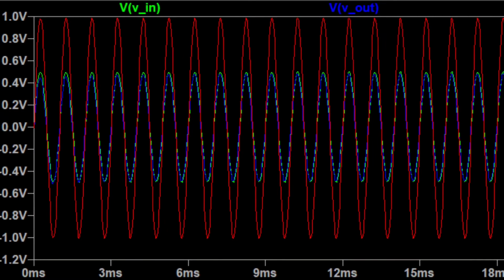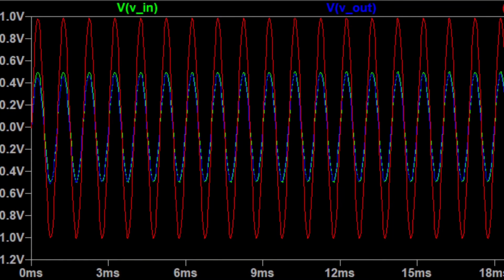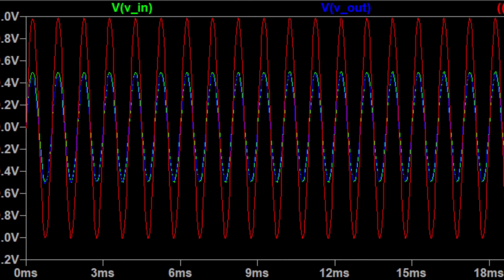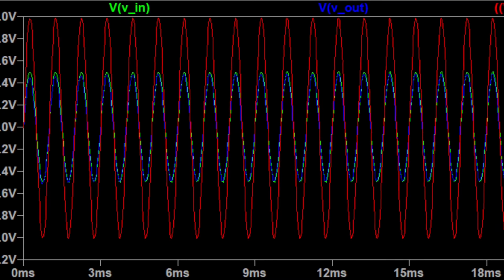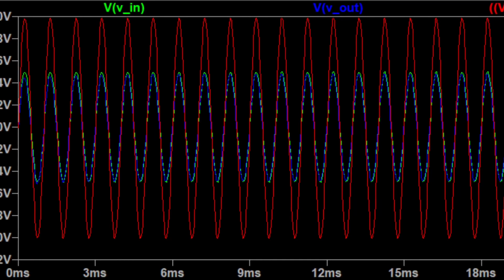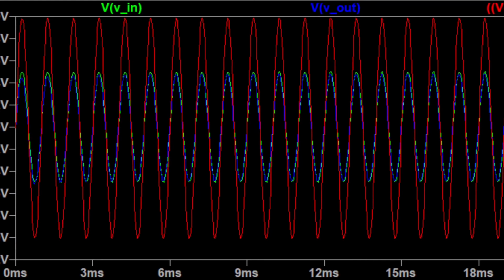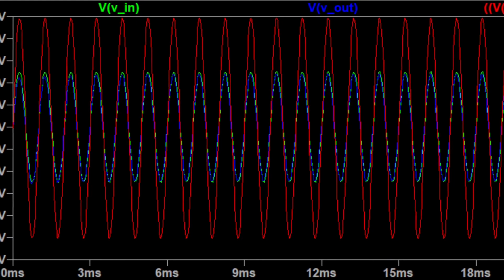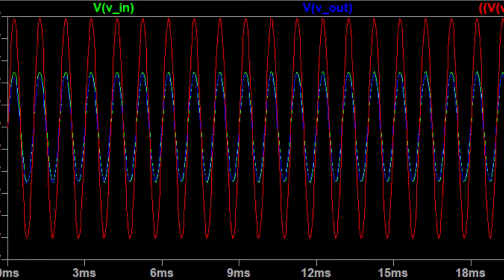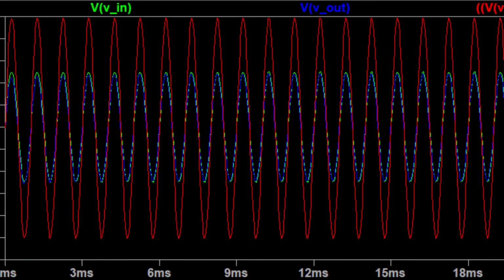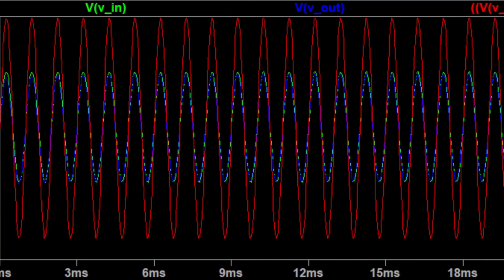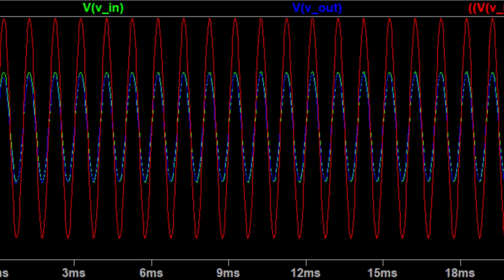To model this transistor in LT-Spice, I used a built-in LT-Spice model for 2N3904. I followed a similar design to the one posted under the Project 3 design module, except I added another capacitor in parallel with RL on the emitter to determine the voltage output, which when graphed, you can tell that the output has almost the same values as the input voltage. They are only slightly off.